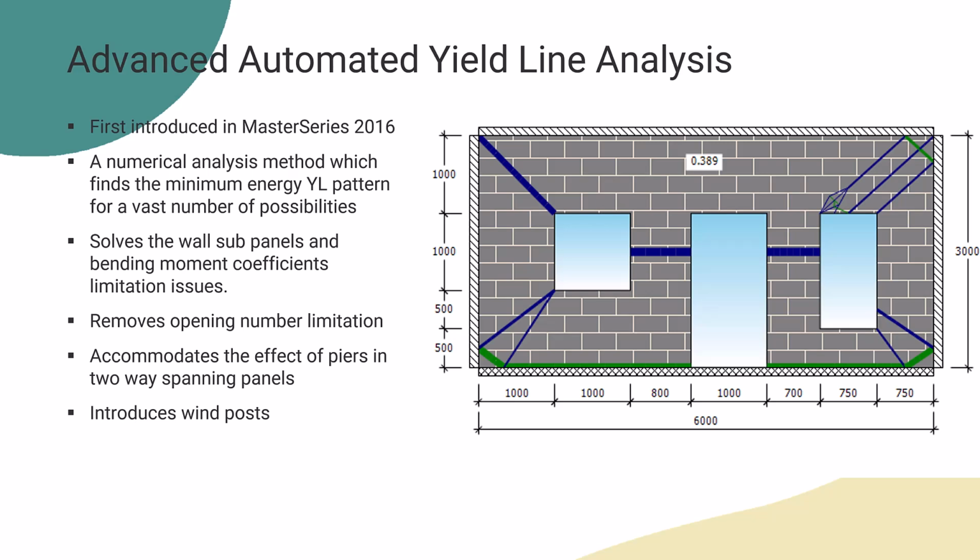If you're up at 0.95, we would maybe say to you that if you're using a coarse mesh, you might want to use a refined mesh, and there are options in the software to do that. The disadvantage of using a more refined mesh is that it bumps up the analysis times and makes the software less instantaneous to work with, so it's not possible to have everything updated instantly with every change you make. You tend to turn off the auto solve in those situations and only solve when you have to, which is absolutely fine.